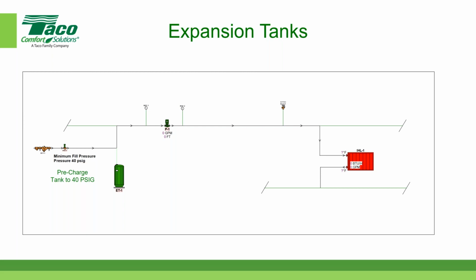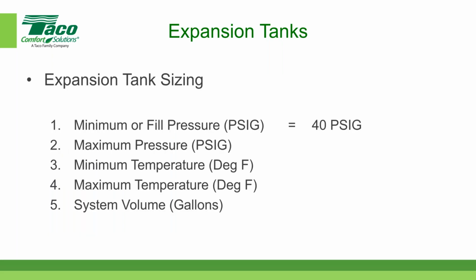You must pre-charge the expansion tank to your minimum or fill pressure before you physically connect it, and you're adding compressed air to the air side of the expansion tank. Okay, let's go on to the next point. What about the maximum pressure?